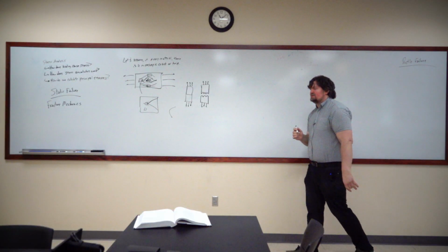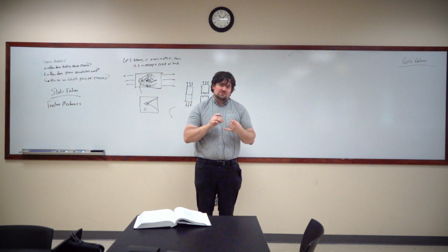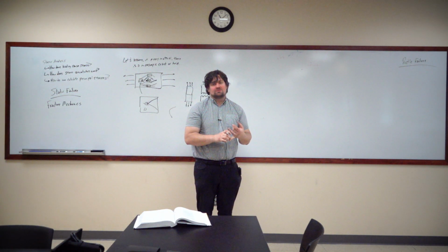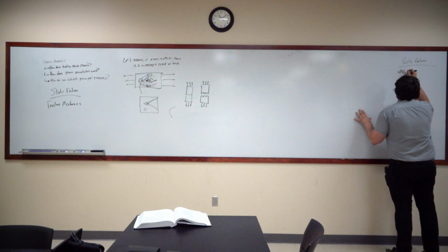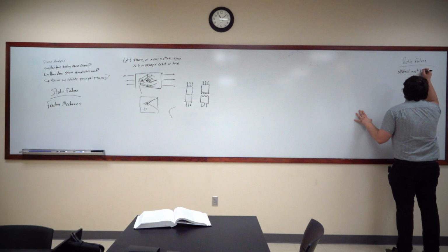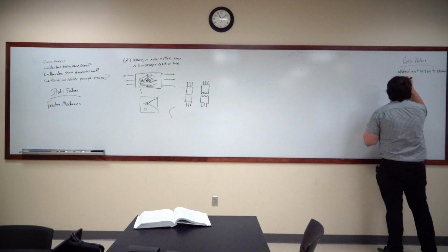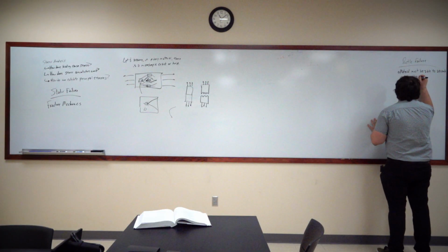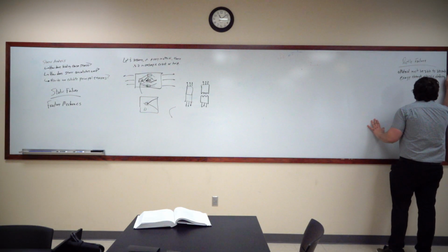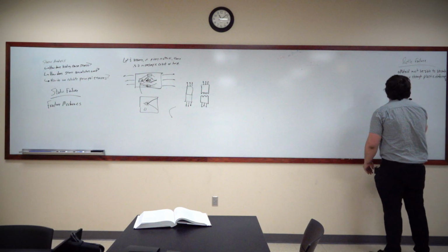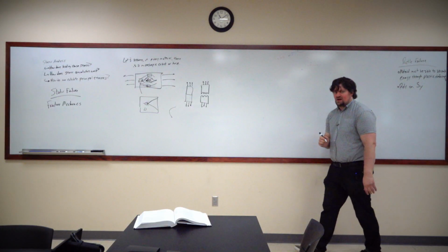Now, the thing about ductile failure, when we're going to discuss ductile failure, is the condition that must be true is the material must be able to absorb energy through plastic deformation. And in ductile failure, this will rely on Sy, which is our yield strength. Okay?